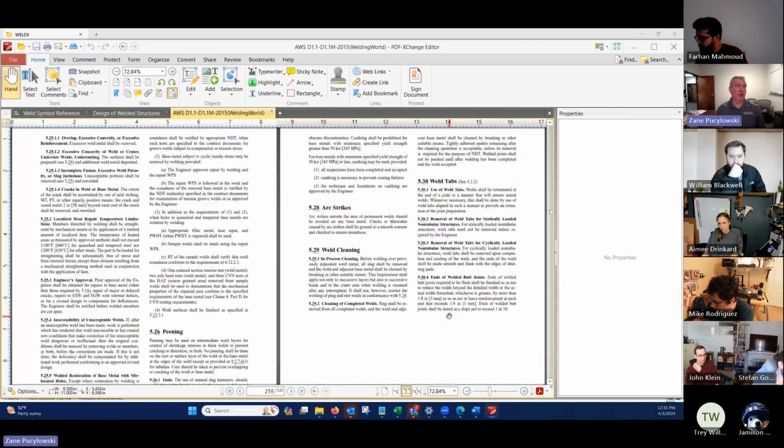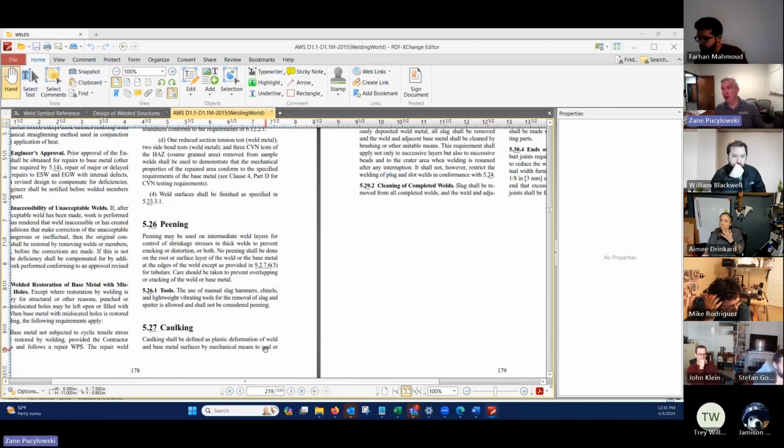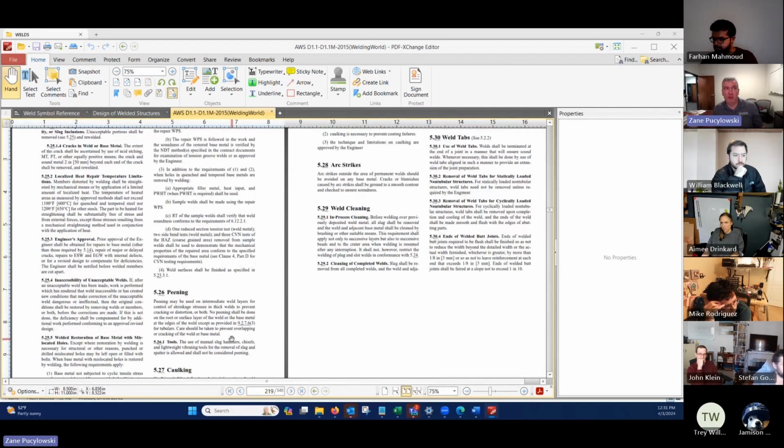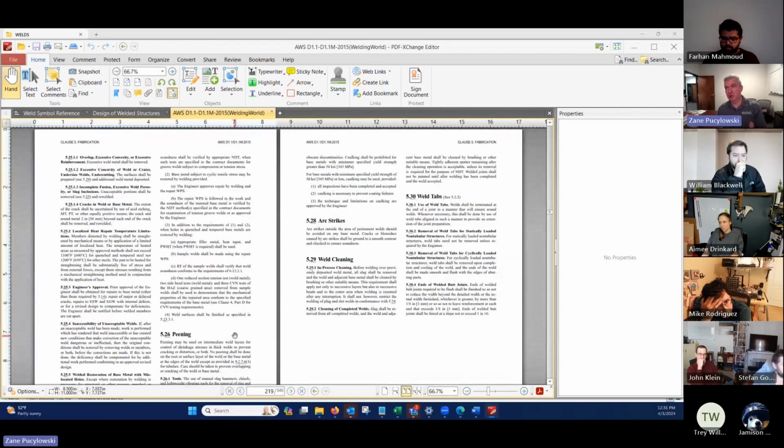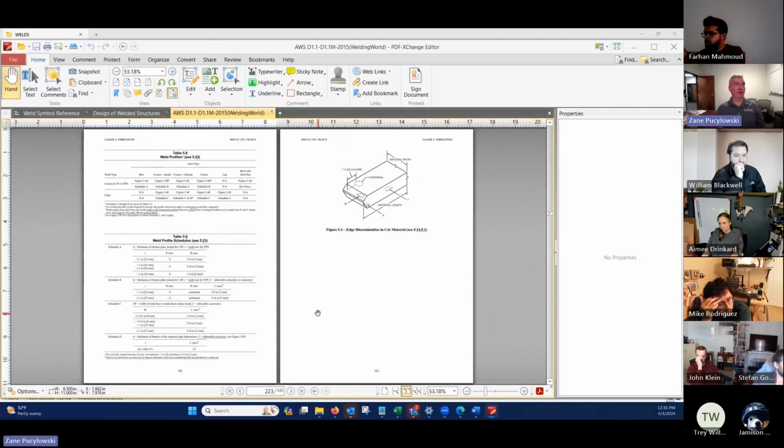And then my favorite section, you guys have heard me and you thought I was joking. It's actually called caulking, when you just weld it to seal it and make it look pretty and not actually have a structural joint. So, you guys have heard me say, are these guys welding it or are they caulking it? Because sometimes we're trying to figure out how much load we can pass through that joint. And if they're shady, sketchy, and it's aluminum, they may literally just be covering the hole. And we might not get a structural joint out of it. We might have to add some material or add something. That makes sense?